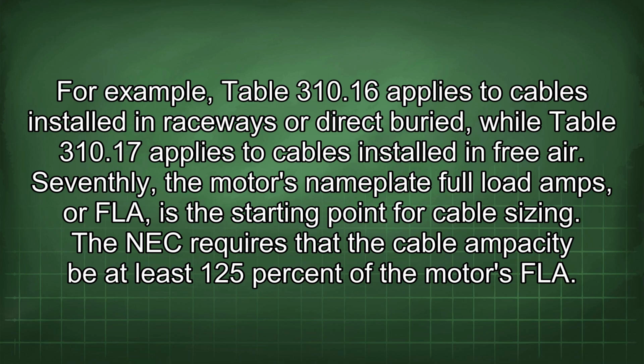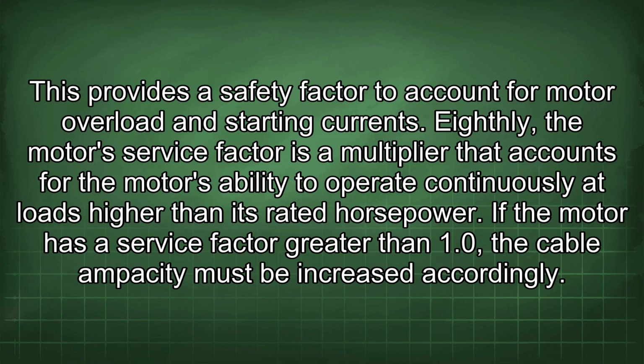in free air. Seventhly, the motor's nameplate full load amps, or FLA, is the starting point for cable sizing. The NEC requires that the cable ampacity be at least 125% of the motor's FLA. This provides a safety factor to account for motor overload and starting currents.